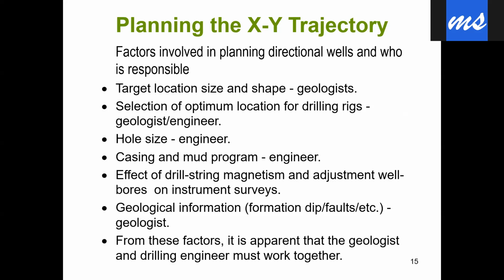And also we need to know the effect of the drilling string on the magnetic field, and adjust the wellbore with the survey instruments, because as you know we are using measuring while drilling techniques to know the survey, or to know the inclination and azimuth, and this type of tool is affected by the magnetic field.